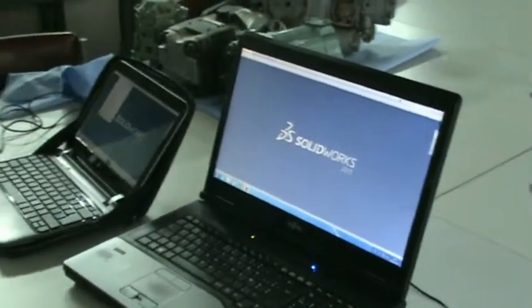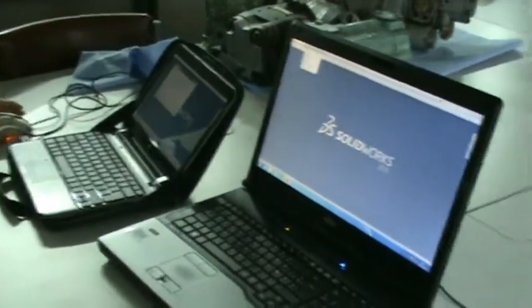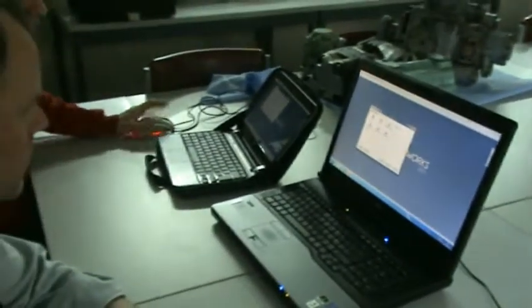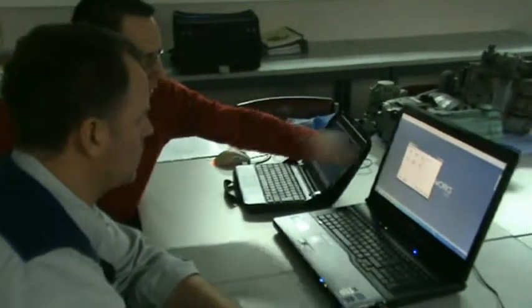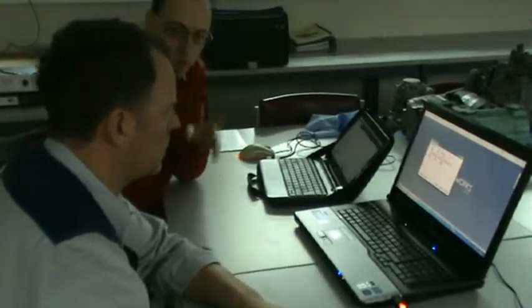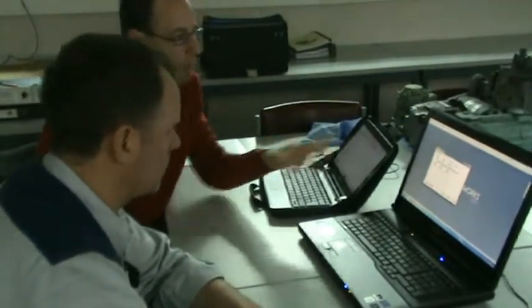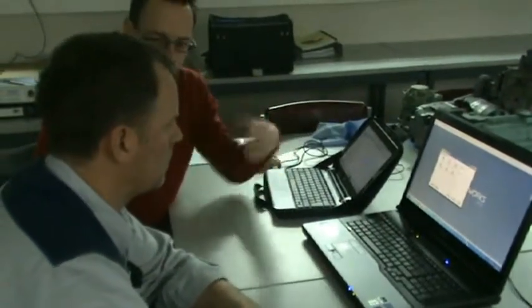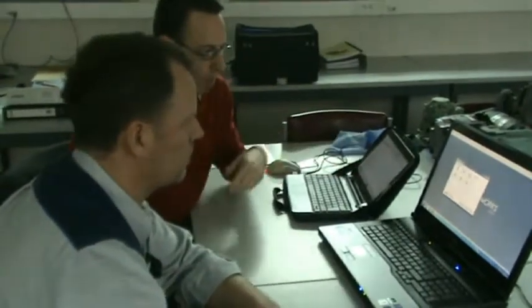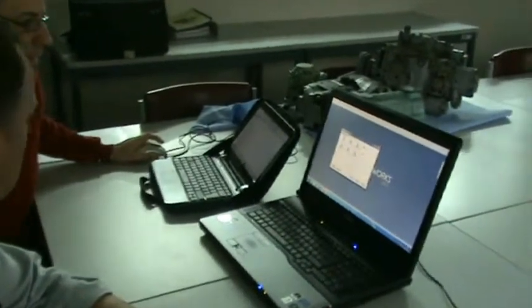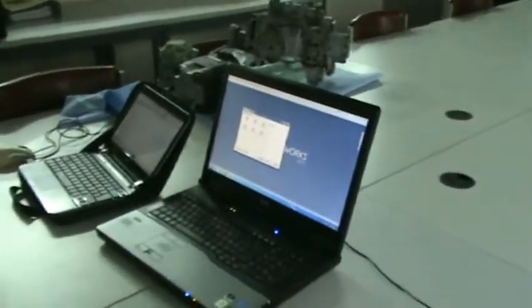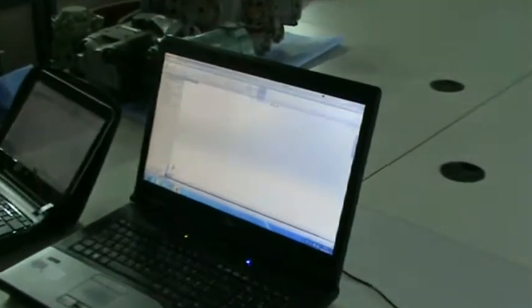We're gonna start a new part. File, new part. You have to watch for the three tabs, the templates. Always take the right one. I'm going to show you why you have to do it, because the standard templates of SolidWorks are not the same as the part I made. They are in inch, I think. Normally, when you install the program, you can choose immediately, but afterwards they are always in millimeter, I think.